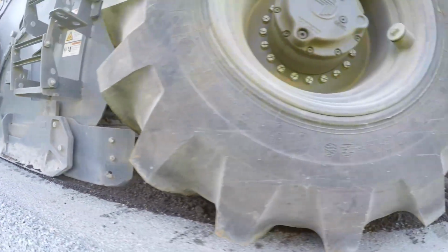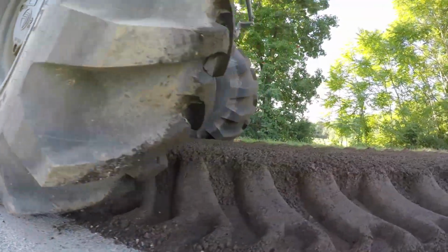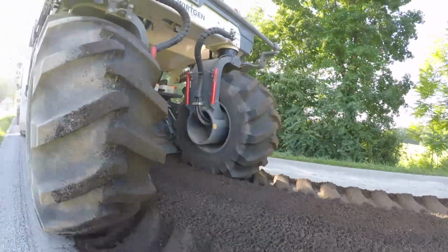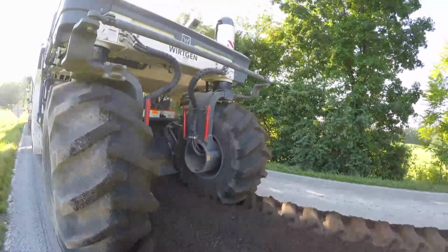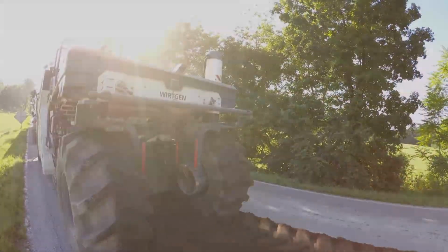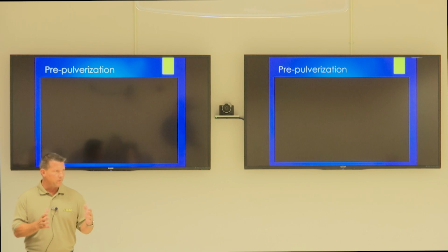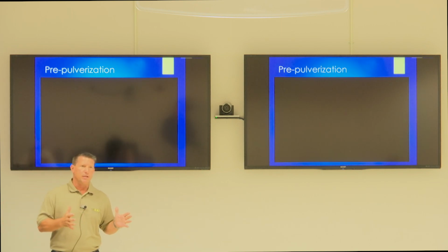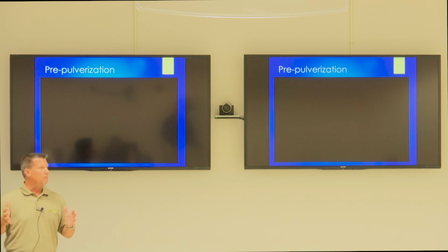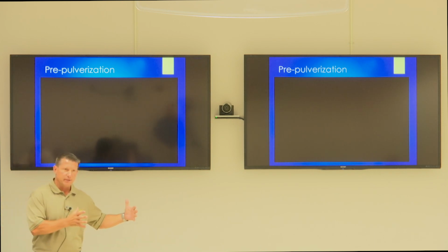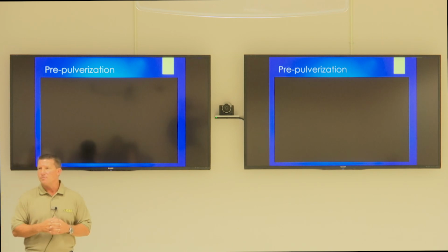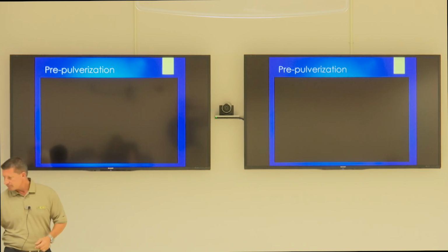And so now what you're doing through here, you're pulverizing that material. And the intent is now you have an opportunity to move that material the way you need to. A lot of times there are projects that contractors worked on, I've seen before, where they've actually taken the road and widened it 4 feet, or they've taken a road section and moved it around a utility, around a super. So you're able to take that material and use it on site. It doesn't have to be trucked. So it's very beneficial in that manner.